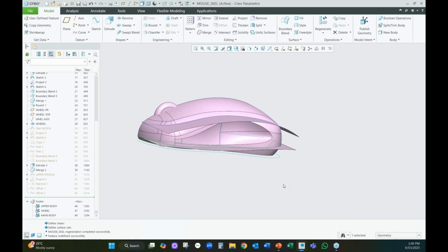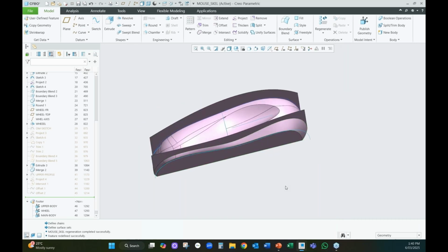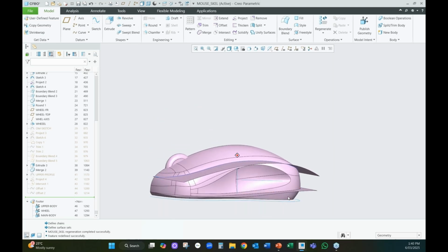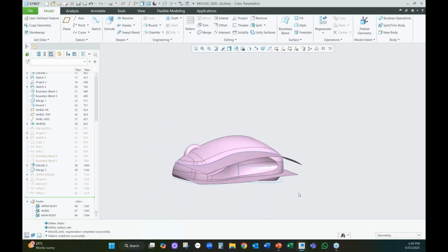But the general philosophy is trying to push your reference control as low down the model tree as possible, so you're not having to overcomplicate your higher level. Also, from a practical sense, if you've got a team leader with two sub teams working under them, and each sub team is responsible for a sub assembly, and this is a process I implemented at ResMed back in 2003, where we had a humidifier team, which was the front edge of the product, and a flow generator team, which was at the back end.